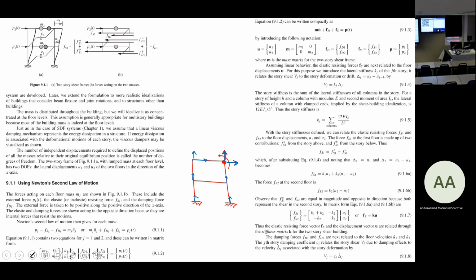This is a good assumption. This is not wrong, because if you really model the slab here with, say, a 20 centimeter concrete deck, you will see the deformations of the 2 sides of your slab are almost the same. So it is a good assumption to take these 2 as 1 degree of freedom and these 2 as another. So with this assumption, we are decreasing 8 degrees of freedom to 6, eliminating 2 more, right? So from 8, we get down to 6.